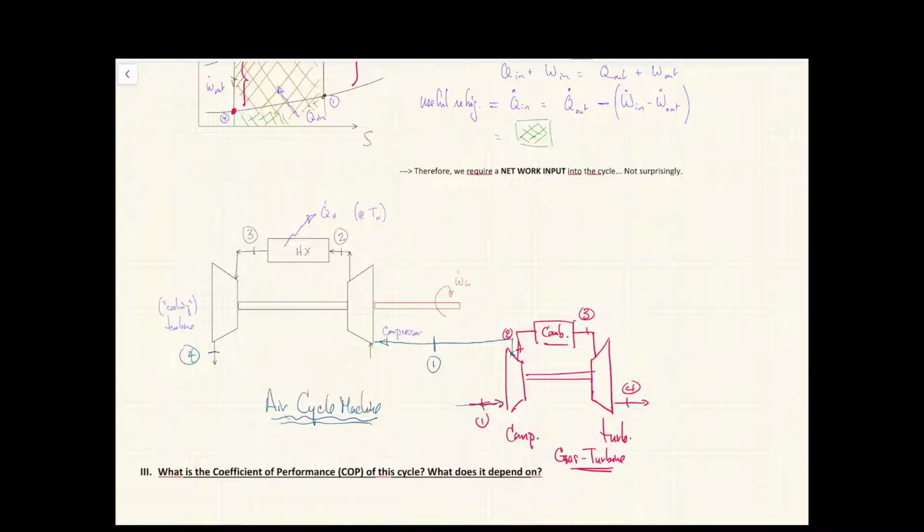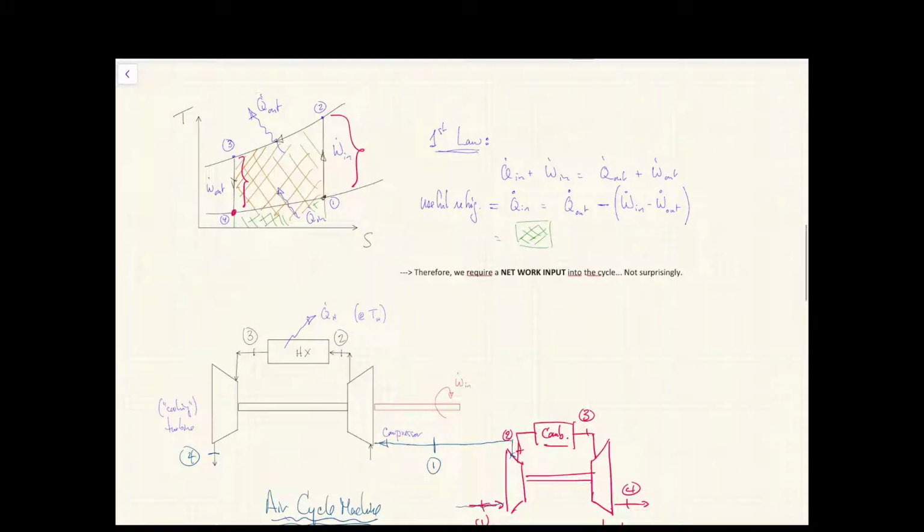Okay. And so back on the TS diagram, this is where the air would come in from the engine compressor. So let me call this maybe my 1 prime point here, so that this distance between this intermediate isobar and the high pressure point of my air cycle machine is exactly equal to what I had on the left hand side through my expansion turbine, which is this guy right there.